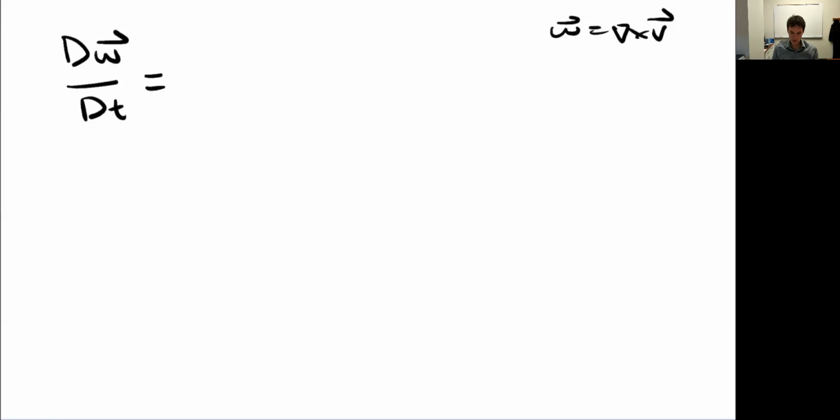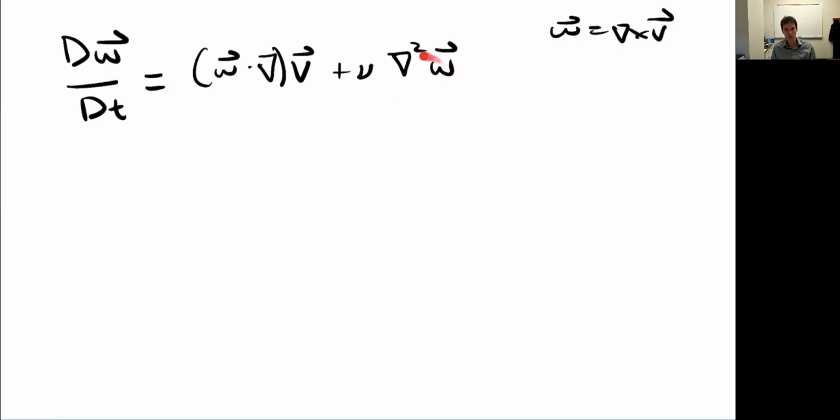And this is a useful equation for many reasons, but one I'll show here to motivate some limitations of some turbulence models. So I get these two terms here. And again, I'm not going to go in detail, as you can see more in the book, but this term here, this is my viscosity. This is the vorticity diffusion. This looks just like thermal diffusion. If you compare it to the heat equation, this is the heat diffusivity. So it's the same idea. It's kind of how the vorticity diffuses or spreads out due to viscosity. This term here is a stretching term.